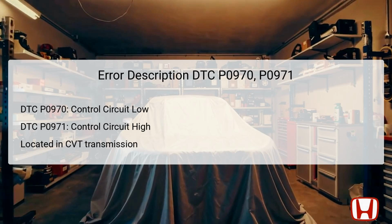Both conditions disrupt the normal operation of the solenoid, which regulates the hydraulic pressure necessary for effective clutch operation. Located within the valve body assembly, this solenoid's malfunction can lead to a host of performance issues if not addressed. Electrical circuit integrity is paramount, as these codes reflect an electrical-based issue, eliminating mechanical failures as a cause.